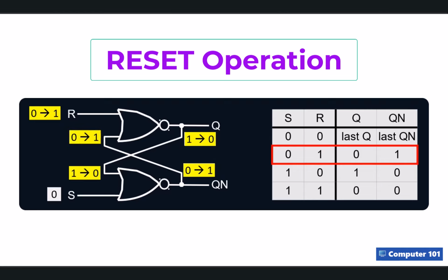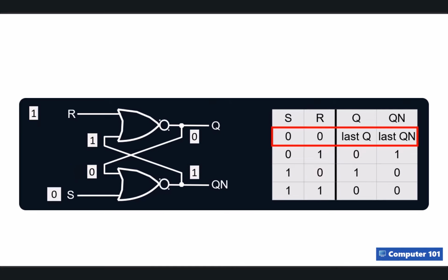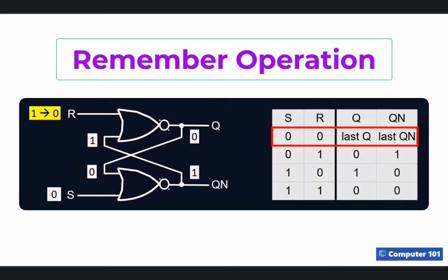And just like before, if we drop both of our inputs back down to 0, the circuit holds completely steady. It remembers the reset. It stays right at 0. Because this simple, elegant little circuit will happily just rest in either the set state or the reset state indefinitely, engineers refer to it as being bistable.